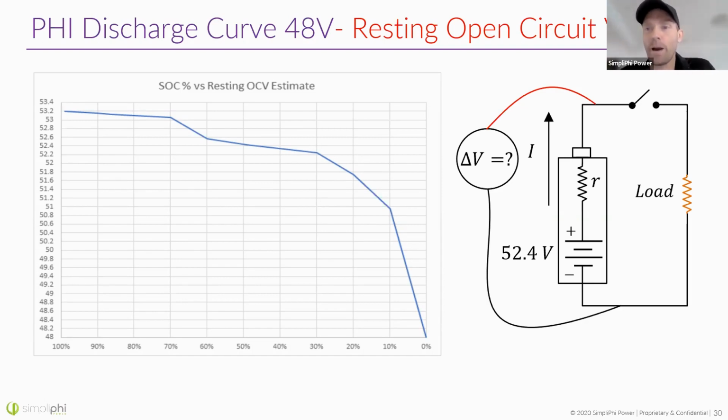What is the issue why lithium batteries can only work down to -4 degrees Fahrenheit? James, good question. Inside all batteries, and I don't have the slide here for it, is what we call the jelly roll, which is kind of a sandwich of a cathode and anode, the positive and negative sides of the battery, and that contains a solution called electrolyte. The electrolyte contains lithium ions as well as some negative ion, typically PF6.